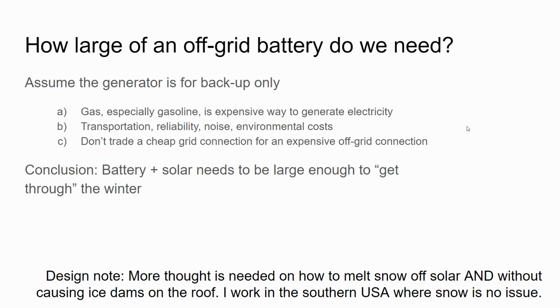All right. So when I use a generator, I'm not trying to rely upon the gas generator. There's things we haven't modeled, like extreme weather. PV Watts is showing us typical weather, but there's still outlying weather events. This year was a particularly bad year for solar production, and system production in my region is down by like 15%. So having the generators there to play free safety. You don't need a large generator.